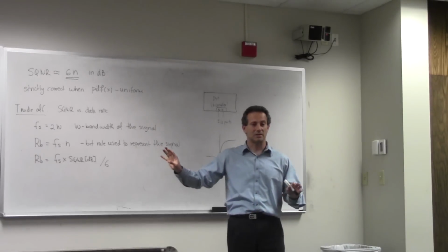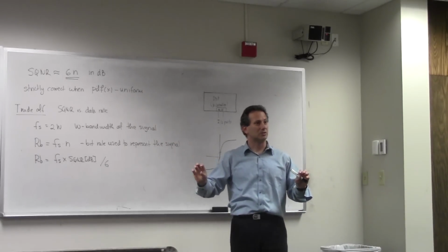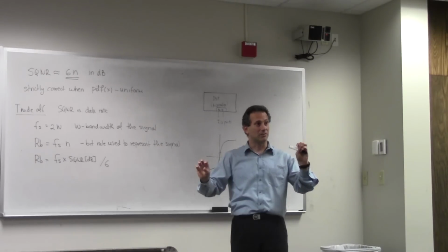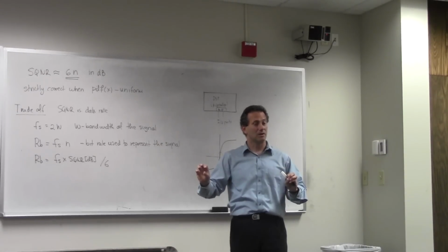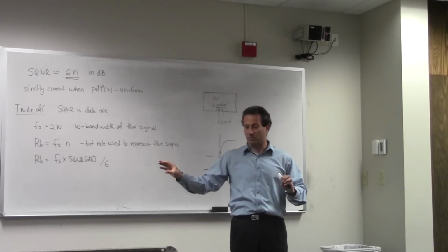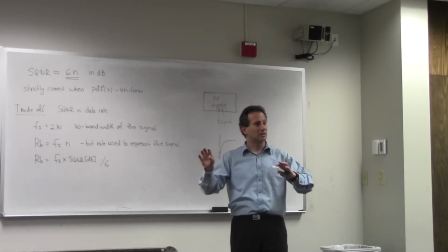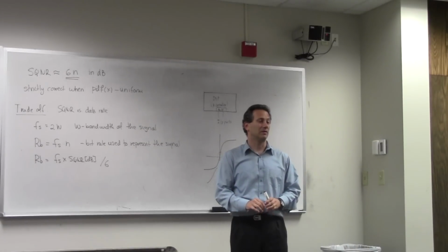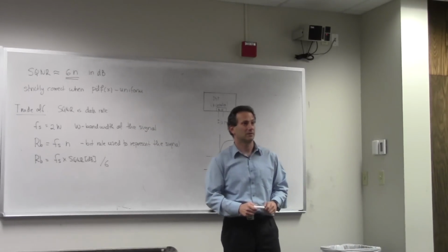We discovered that the SQNR depends on the PDF. We discovered that the PDF may actually adversely affect your SQNR, and what we need to do next time is devise an engineering solution for that, and that would be non-uniform compression.